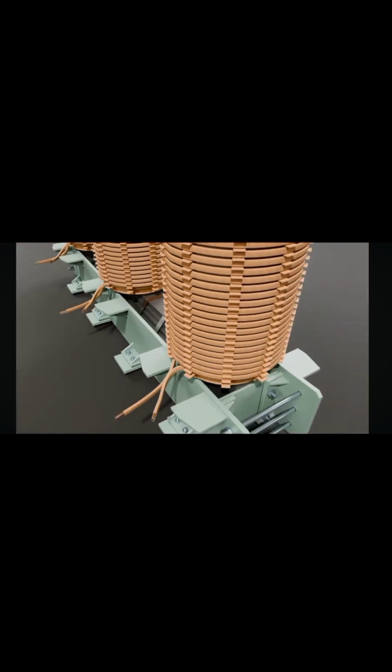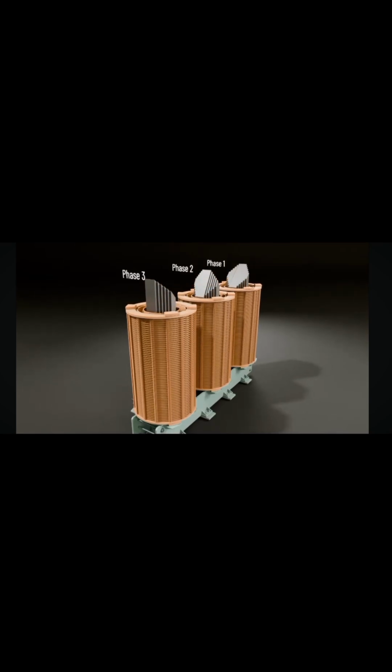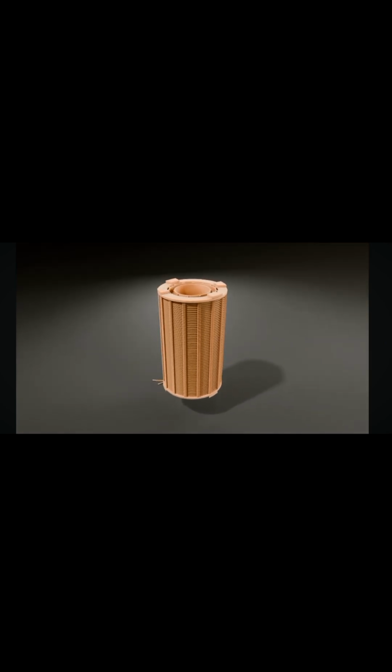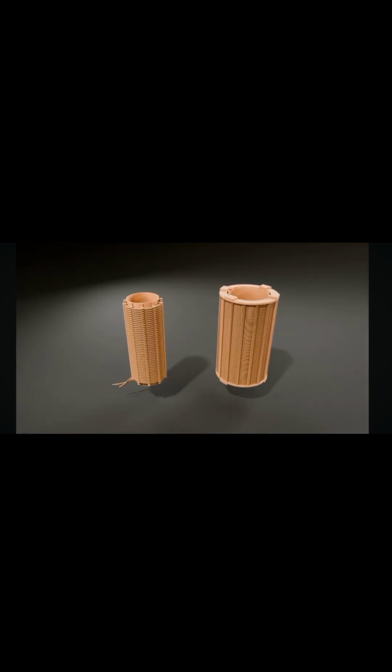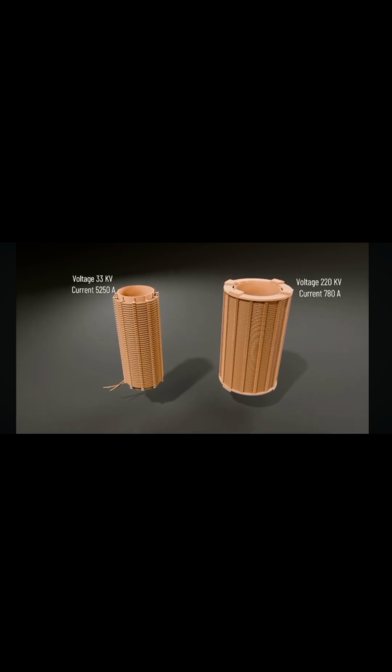In a 3-phase transformer, each phase consists of a pair of low voltage and high voltage windings. In a low voltage winding, the number of turns are much less compared to a high voltage winding. As the name suggests, the voltage level in the LV winding is lower than in the HV winding, and the current is very high according to the transformation ratio.